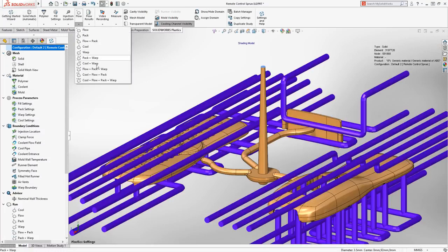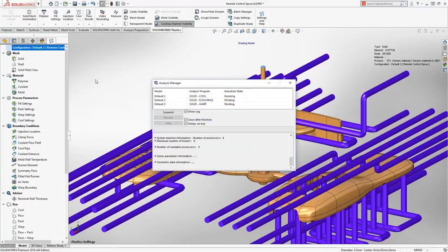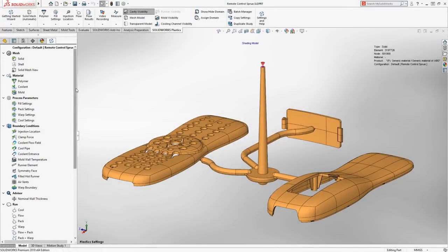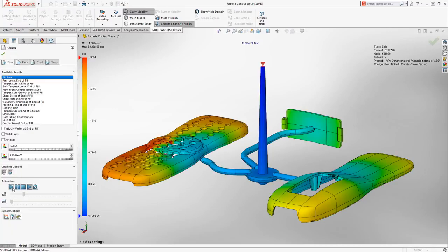Once the simulation of your molded components is finished, you can evaluate the results to determine how those parameters alter your finished plastic injection molding products. In some cases, you're looking for immediate information, such as determining fill time of your cavity, or more importantly, if your specifications will result in a critical failure, such as a short shot. SolidWorks Plastics helps determine the optimal parameters to determine conditions like these and optimize the overall fill process.